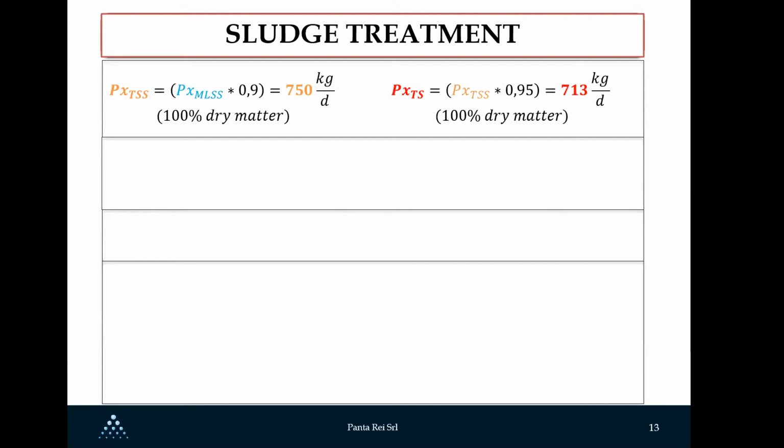In an easy way, we can calculate the sludge after the thickener considering the moisture, because as we know, after the thickener, the dry content is in a range of 2–3%. In this example, the wet sludge is 30,000 kg per day.